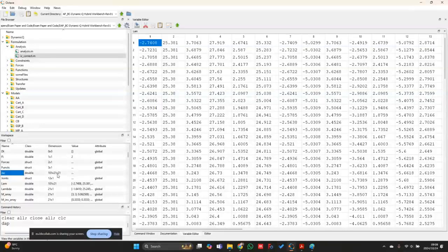So the first 21 is with regards to the constraint number. So that always corresponds to the Lagrange multiplier that you are referencing. And then the last 21 over here is dependent on the number of bodies that you have. So each of them have 3 coordinates. So it's 7 times 3 in this case, which also gives you 21.